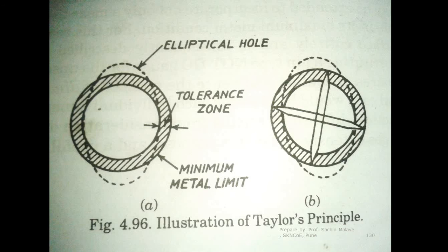the go end is going to pass here. The cylindrical go end is going to pass. There is no issue with the shape of the go end of the cylindrical gauge. Remember that the go end should be cylindrical. There is no issue. So if you pass the go end through this hole, it is going to pass.